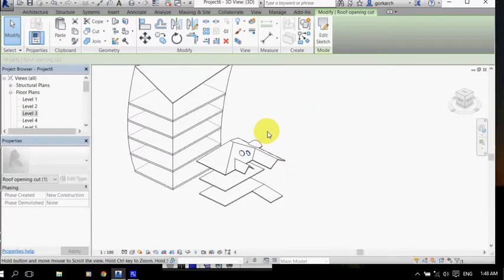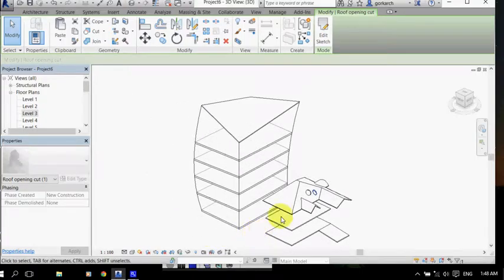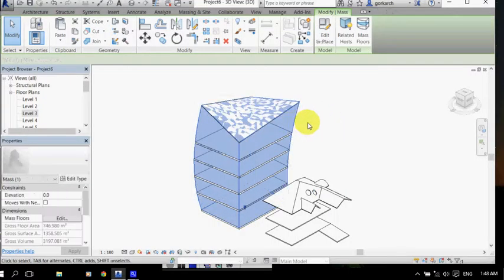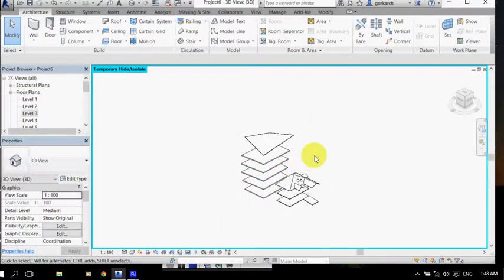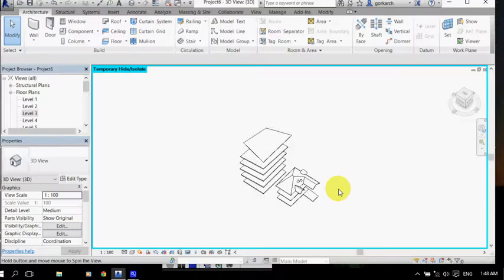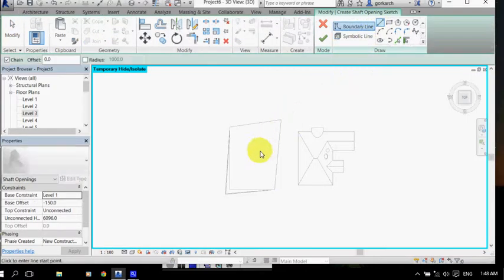In terms of openings, it's also important to understand that you can, for example, select the shaft opening. So I'll do it for a multi-story building because it becomes very effective if you have a number of floors. I'll hide my mass, and I'll do something like this. I'll go to a top view, I'll create a shaft opening in this area here.